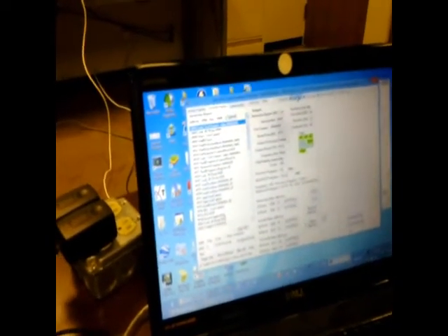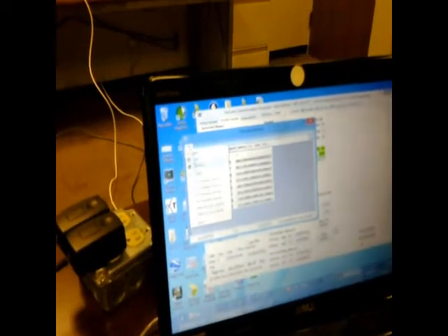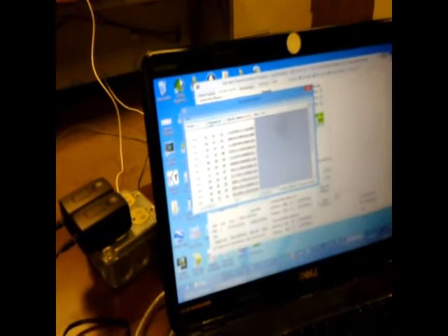This is the user interface software that allows the user to write the test procedure as a test program, specifying whatever test they want to apply, to select one of the IPs on the chip, apply whatever test they want. It allows the user to download the test program to the test processor, upload it again to check if it's correct, to view all the register contents, to view all the memories on the test processor, all their contents, download new contents, upload them, even modify some parts and download them again.